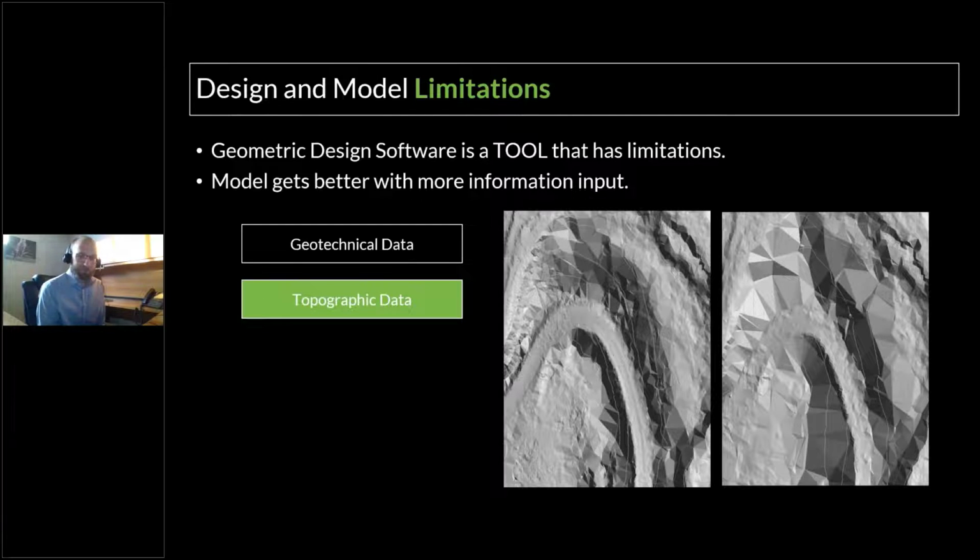So as we've acknowledged that there's limitations, it makes sense to consider those limitations as you design. So ask yourself, what if variable X isn't reliable or I made a wrong assumption? Will it make this project infeasible, cause environmental damage, or cause cost overruns during construction? If so, is it manageable? Can I reduce the risk with additional field investigations and design revisions? What are the requirements for construction monitoring, supervision during construction, etc.?